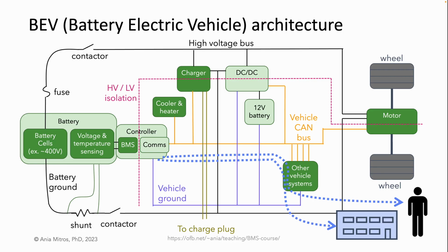As another example, if we lose a cell voltage sense wire, we don't have an immediate safety issue, but it is unsafe to charge, and the vehicle may warn the driver to please head to a safe destination and call for service. For Internet-connected or cell-connected applications, the system may issue an alert or send data back to the manufacturer. Some of that data or alerts may come from the BMS.